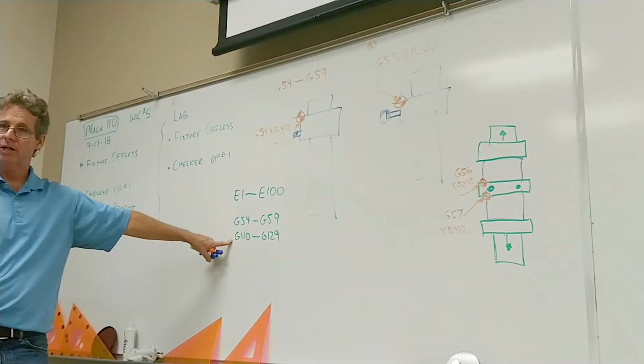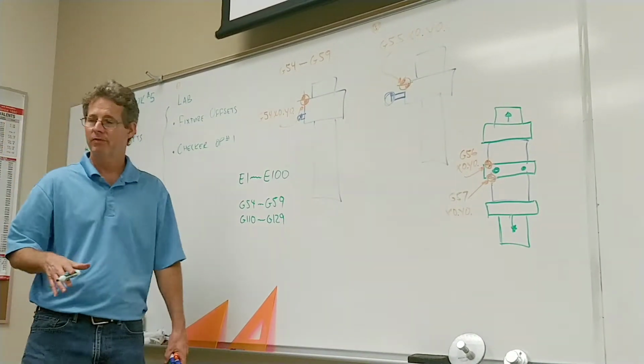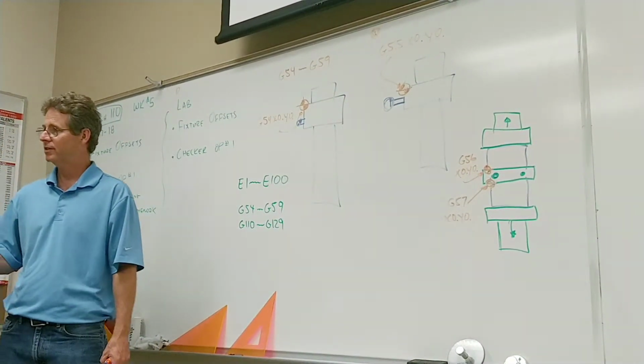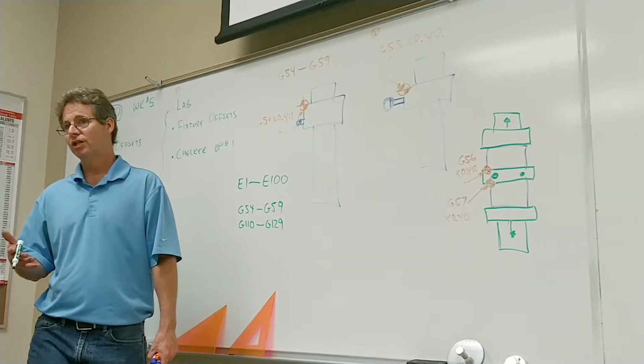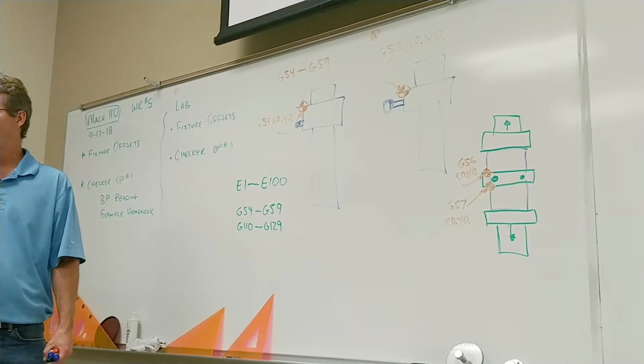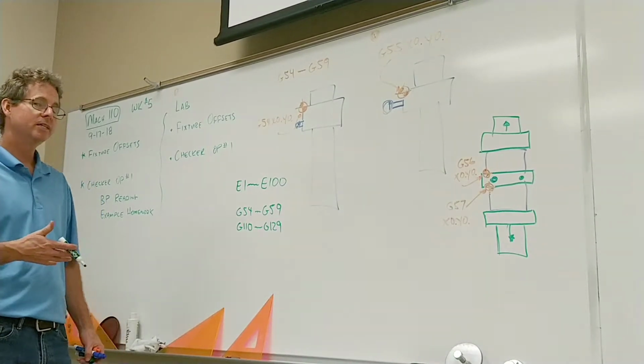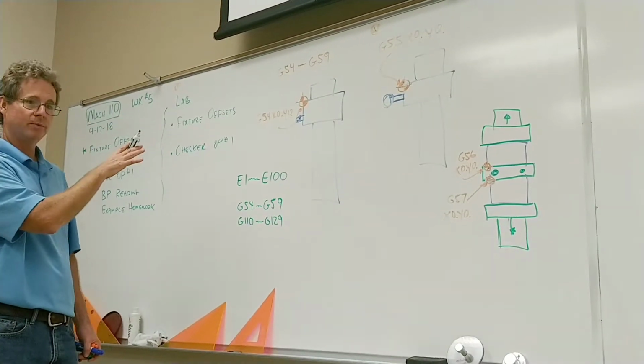Now, we do tool and die work. So in tool and die shops, we're typically reinventing the wheel. We have a new setup, a new job every single time. We're always having to indicate things. Okay? If you're a production shop, that may not be the case. If you're a production shop, you can think about your tooling and make things so you really don't have to indicate things, with some sort of common system.